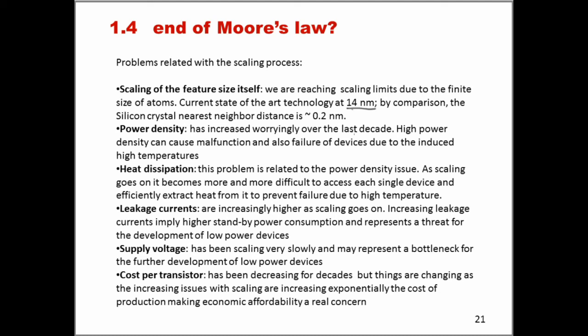The other problem, as we briefly said previously, is leakage current. As we shrink, we have to shrink everything. We have to shrink the channel of the transistor, we have to shrink the gate oxide, and all these processes cause an increase in the leakage current, which means an increase in the standby power of our devices.